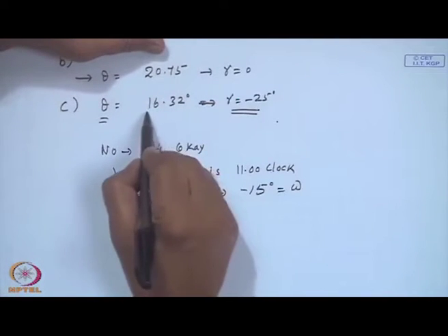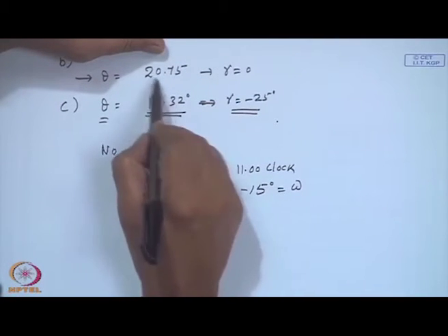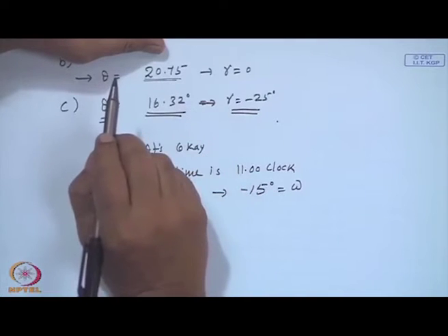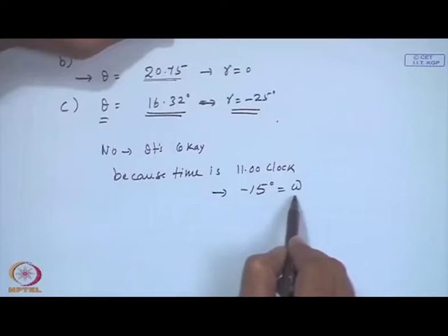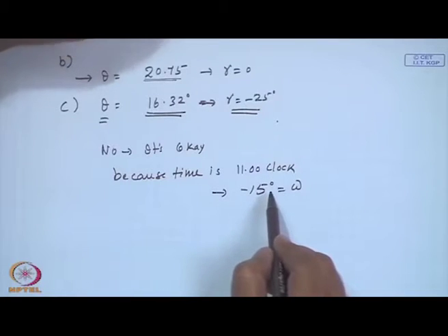Consequently, you have a better angle of incidence compared to even the south facing surface with gamma equal to 0. If you do the same calculation at omega equal to 0, the south facing surface will have a better angle of incidence than the one with gamma equal to minus 25. Better angle means theta is lower.